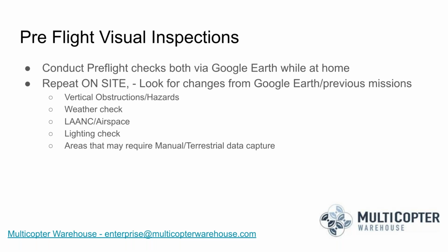a field. Using Pix4D with a Mavic 2, is it best to set the picture trigger mode to safe mode? Well, being in safe mode, the drone will stop at each photo location. So for smaller project areas, yes, it would be better, but ultimately you'll run into issues where you're just not able to map as large of an area, and everything's a trade-off, if you will.